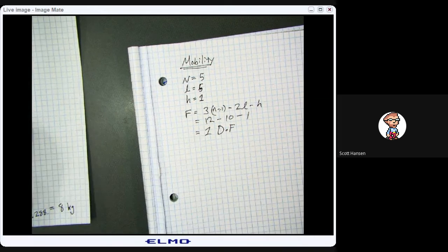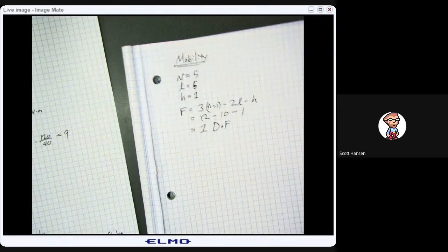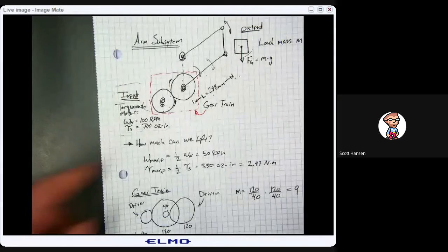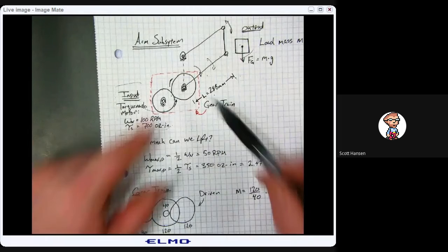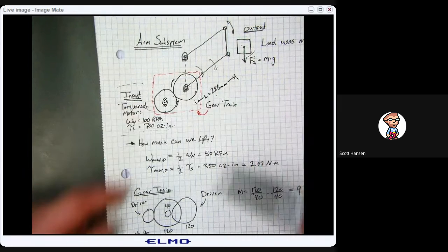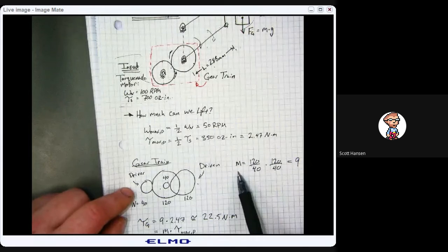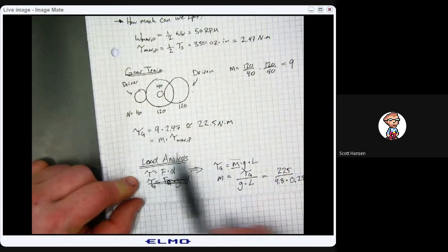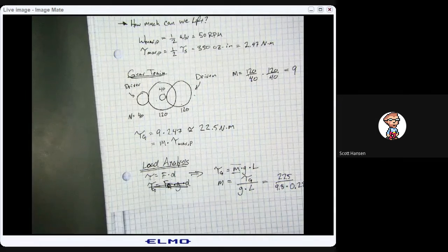So one way of creating a mathematical model for a mechanism is looking at the mobility equation. So it doesn't strictly have to be force equations like this. But if you have components like gears, we can figure out what the operational parameters are at max power. Motors. If you have mechanisms like gears or sprockets, we can do a gear train analysis and figure out what the gear multiplier is. If we're trying to lift weights, we can do simple force analysis, looking at the weight due to gravity and normal force and applied force and that kind of thing.